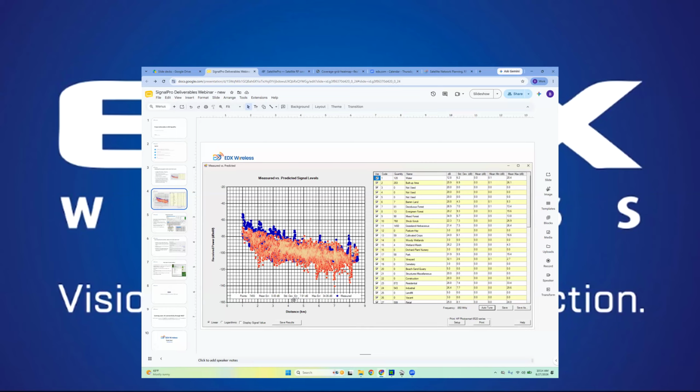And then we've got this standard deviation of that error. And we have a maximum error value, which is interesting. It means the biggest delta we saw was 34 dB between predicted and measured. But this standard deviation allows us to quantify how much more variable the real world is than what I'm predicting for on my map, which is obviously something of a simplification of the real world.